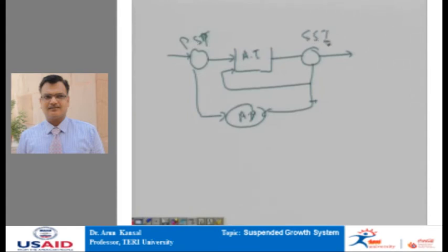So at times if sludge bulking happens, we can bypass the primary settling tank and allow inorganic solids to enter directly into the aeration tank or secondary settling tank. By bypassing the primary settling tank, we are allowing some inorganic solids to enter into the secondary settling tank, and these inorganic solids, since they have high specific gravity, tend to form compact sludge.